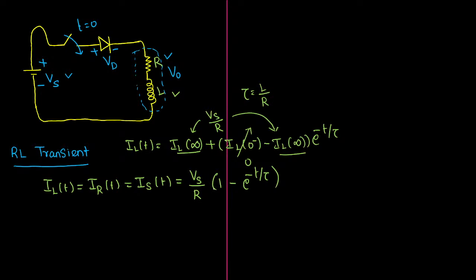Now it's time to explore the voltage across the inductor. You know how to do that. That is the next most repeated question for this circuit. The voltage across the inductor is V equal to L into di by dt. That is, V equals L into d IL of t, the current through the inductor, divided by dt. How will you do that? L into, just differentiate the above expression. See, this is IL of t.